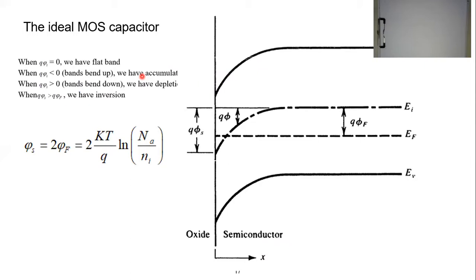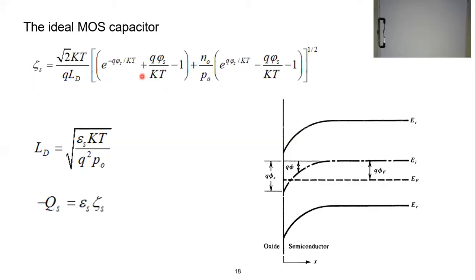Starting from phi, which is the potential, you can calculate the electrical field, knowing that the electrical field equals negative d phi by dx, and then you can go another round by differentiating the electrical field to calculate what's called rho, or the charge accumulation. Of course, I will not ask you to do this step by step. In case you need this equation, I will give it to you directly in your formula sheet in the exam. But let's see how we can reach the same graph using a very conceptual way instead of mathematics.